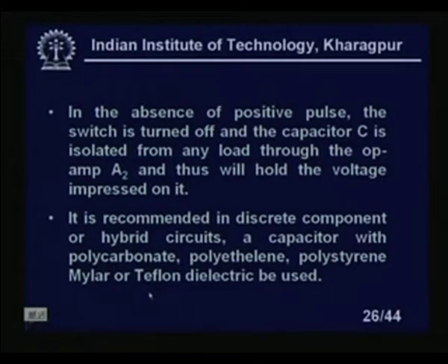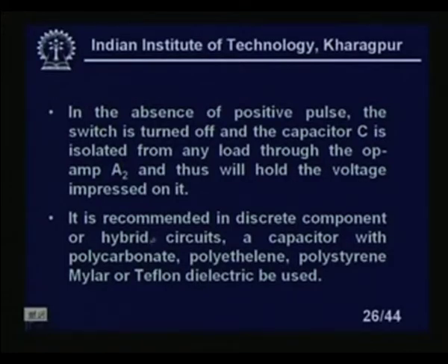We will discuss the different types of capacitors typically used for making sample and hold circuits. In discrete component or hybrid circuits, it is recommended that a capacitor with a polycarbonate, polyethylene, polystyrene, mylar or Teflon dielectric be used, because all these names came from the typical dielectrics for capacitors. This is the dielectric which is placed inside the plates of a parallel plate capacitor. We are not necessarily talking about parallel plates; it can be foil type also, as it happens in the case of electrolytic capacitors.